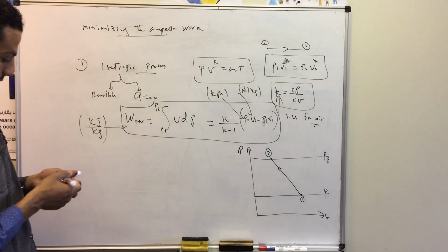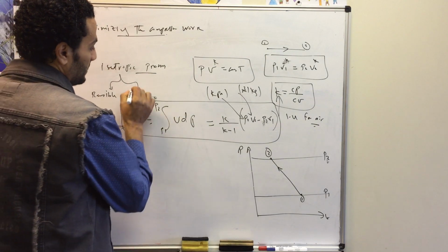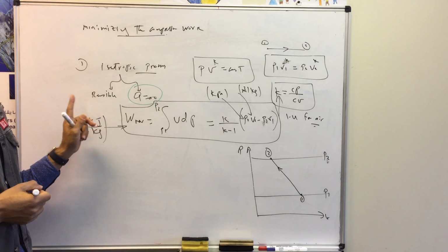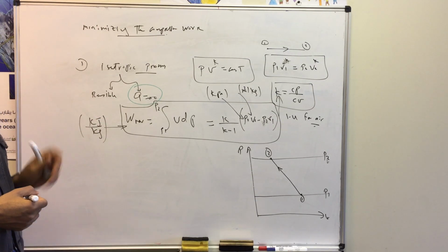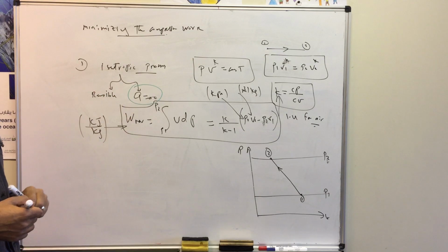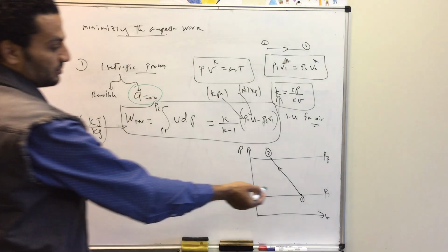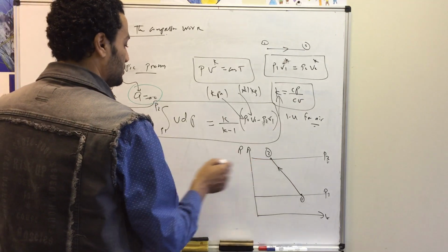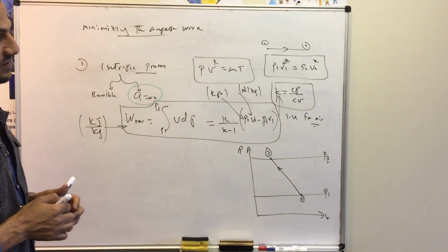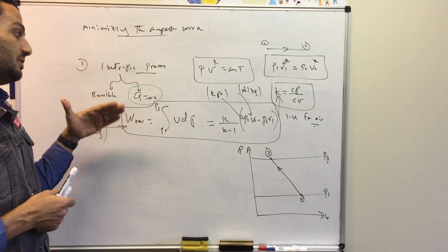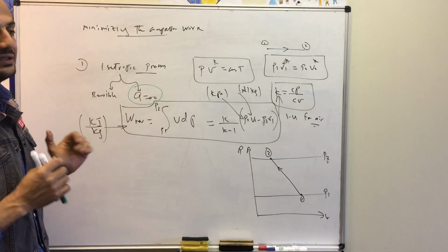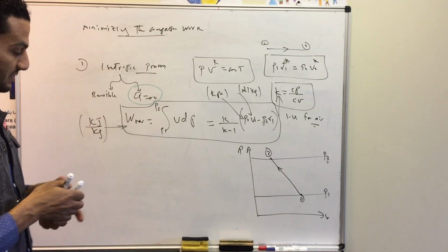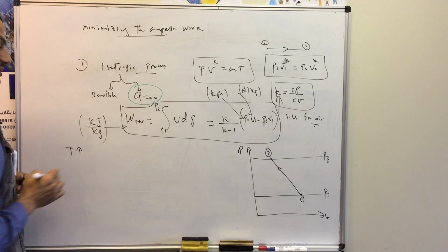But in this case, the system is adiabatic for an isentropic process. You will see that for the isentropic process, the system is reversible, but it cannot result in the minimum work to the compressor because the system is adiabatic. While in the compression process, we don't have any heat transfer from the system. So in this case, the final temperature should be increased due to the pressure. The temperature will be increasing, and as we don't have any heat transfer, the gas will keep all of its energy. So the final temperature will be high.